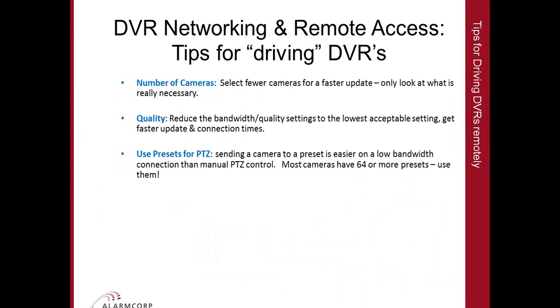configured. And if you do take the time to configure up to 64 presets, even if they're only a few degrees of travel, it actually makes it very easy to almost walk a camera along a perimeter just by recalling presets. And it is a lot faster than if you were to try and drag that camera manually. So the hint there is, cameras have presets, it takes very little time to program them, use them.